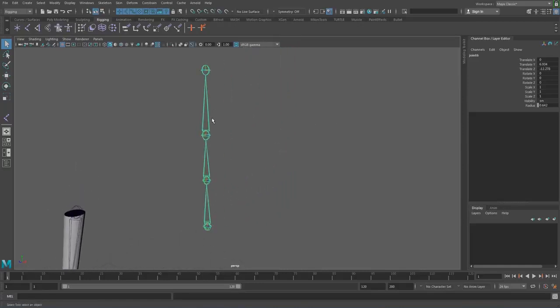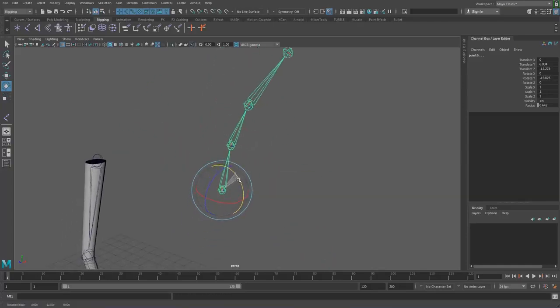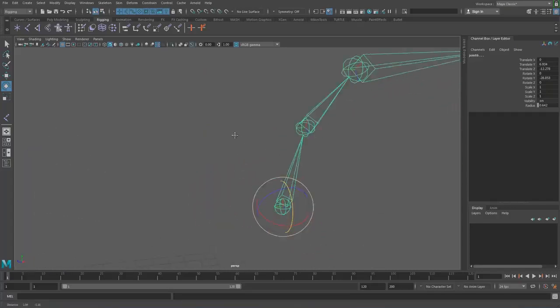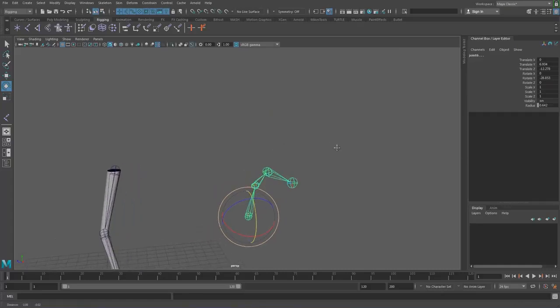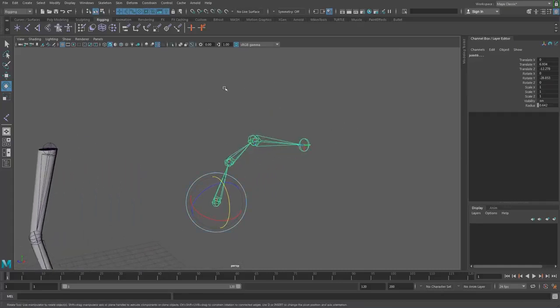And what we can do, if I was to select these joints, if the orientation for these is the same, I should get a nice curl of the joints. Now if the orientation is different, say for example all of these aren't the Y rotation, you can see the Y rotation is this way, then you'll start to get these kind of starting to deform and warp in different areas. So just before you're finished with a particular joint chain, just make sure the orientations are correct.